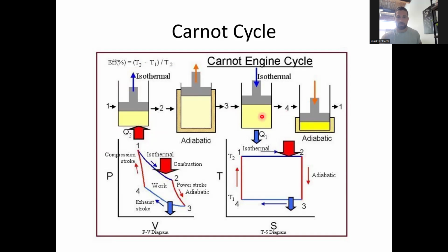And then on the cooling, we're contracting, so we're actually doing work on the system. So this is a net negative component. Based on the differences in the hot temperature and the cold temperature, we can produce an amount of usable work from this cycle.